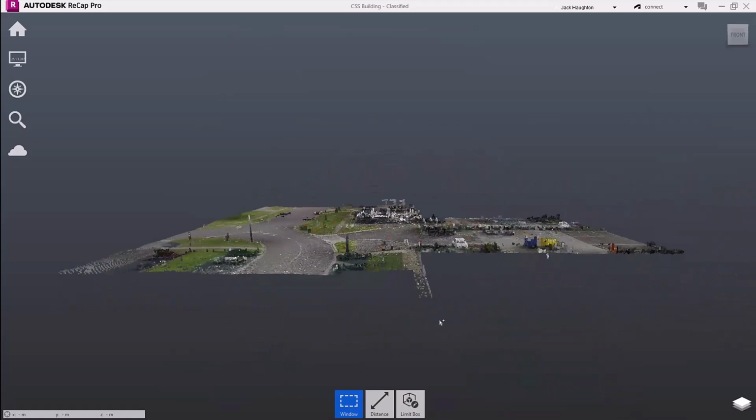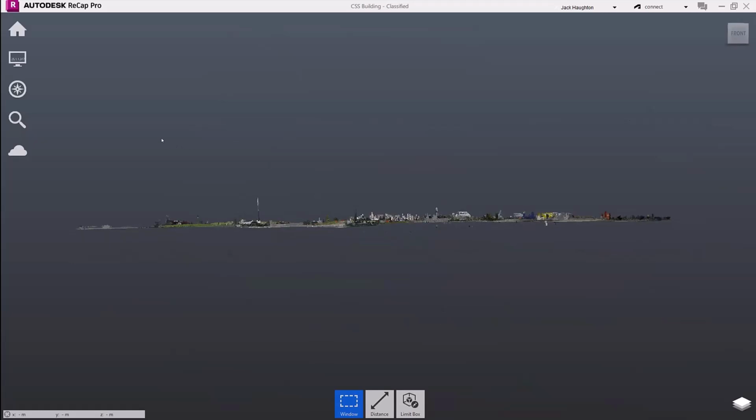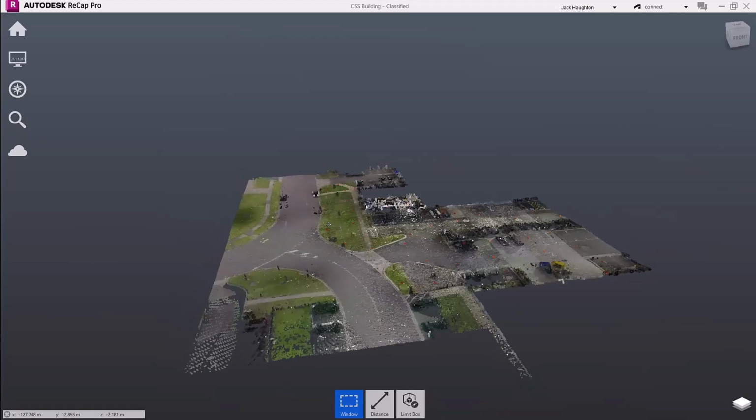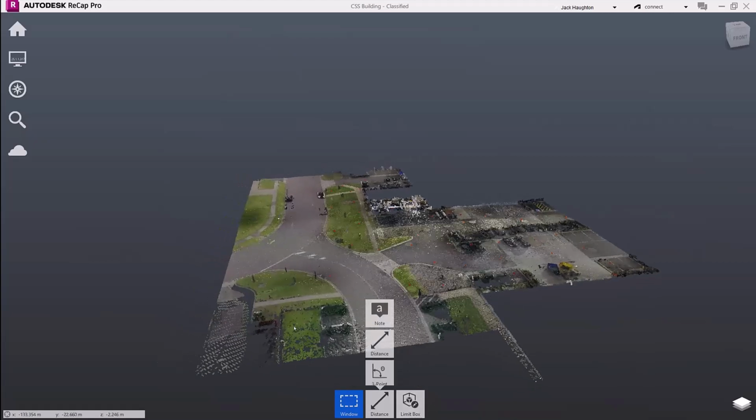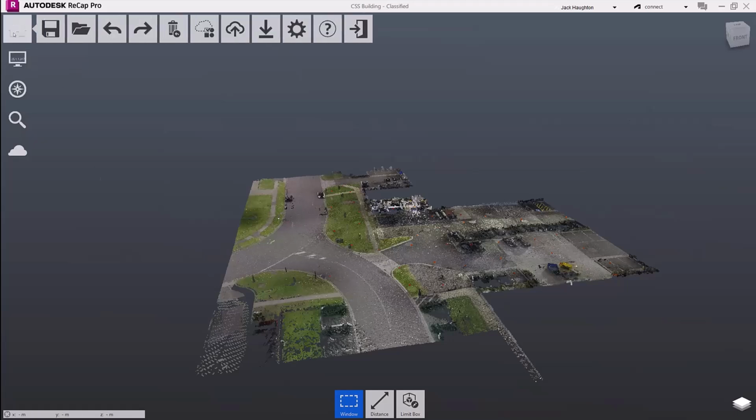On the other hand, if I wanted to delete it, not on a permanent basis, but a more advanced basis, I can select everything again, and this time go delete. If delete is run, you'll see there's no undo option. I can't quickly go back, but provided you don't run save as, you can come up to home, and there is an option here that allows you to recover deleted points. Any points that have been deleted, including by the classification, will be brought back by this option.